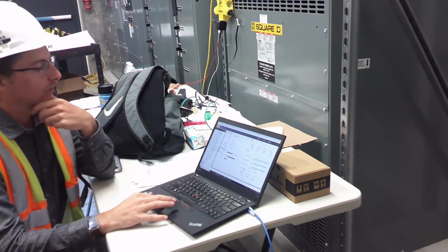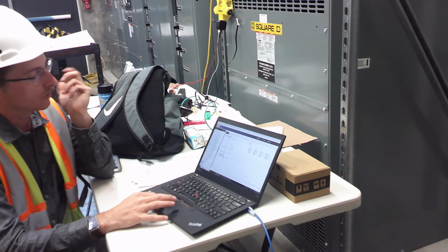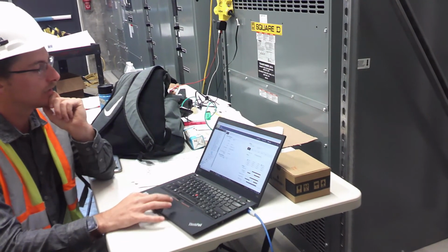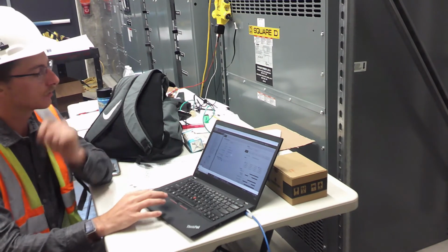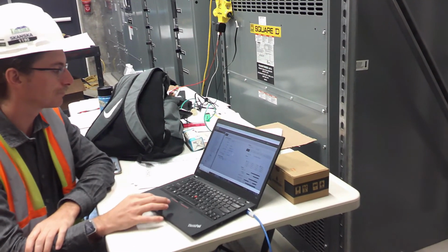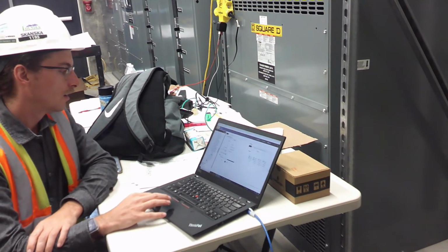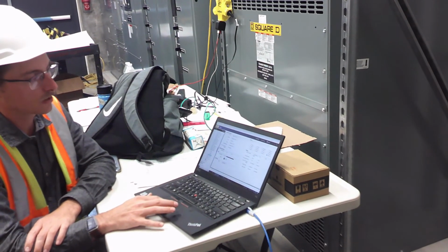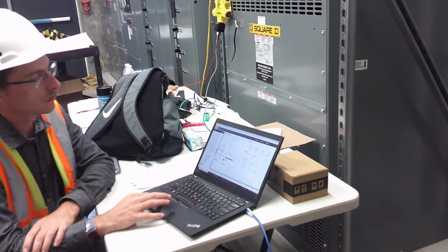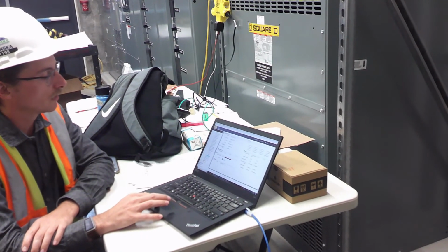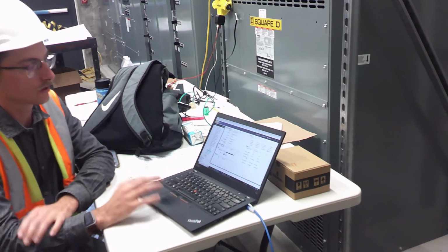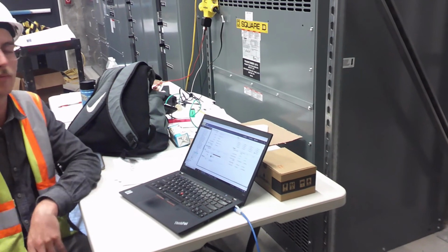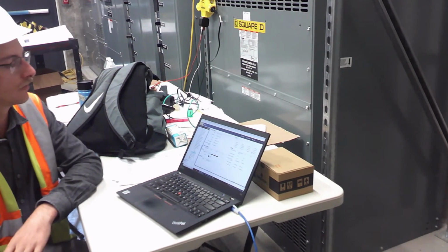Then you got your aux sensor, photocell switch, just the same as the app. Same settings, just a little bit different view. And then all your relays in the panel, you'll see those are in group 16 on occupancy mode. So they'll listen to the occupancy sensors and just turn on without any interaction with the switch.